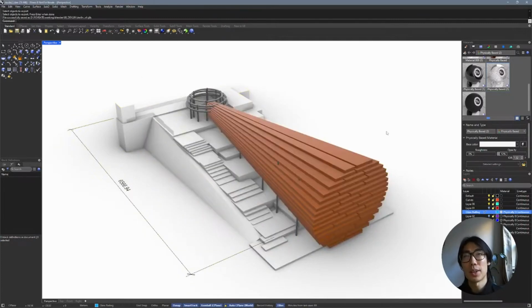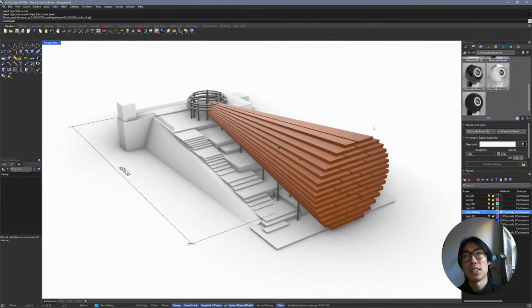Now the great thing about Rhino 8 is this GLTF exporter is now natively built in using C++, so it's super fast. The other versions of Rhino before Rhino 8 unfortunately do not have this, so they're a little weaker in that sense. You can use the package manager to install a GLTF plugin, and that works as well, or you can export out an FBX or 3DM from Rhino to Foveate. The downside being those are much bigger file sizes because they don't support compression and cannot be optimized as well, but they are doable. So now we've exported this.